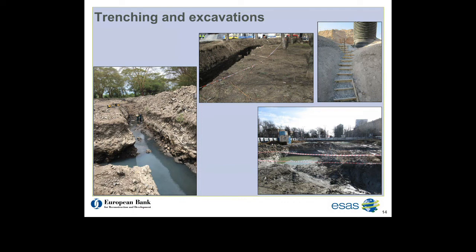Two means of access and escape is not always provided to deep excavations. Furthermore, where access is provided, it is of poor quality, with homemade ladders, no handrails, loose stones and trip hazards, and other problems preventing safe access. Some of the excavations are deep in slippery clay with no means of escape, and there is no rescue equipment, such as a buoy or a line. Some of the trenching is also being undertaken within the community. These sites are not fenced, and the public can access the works.